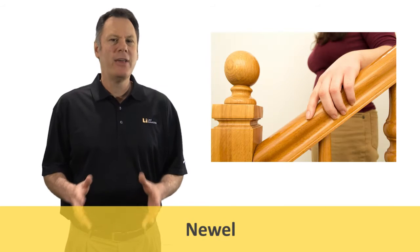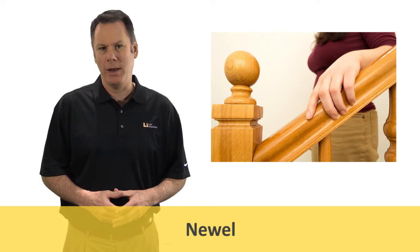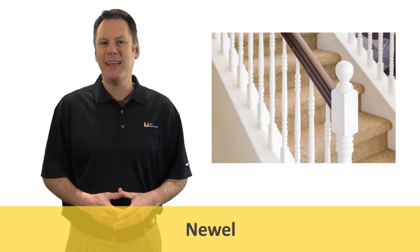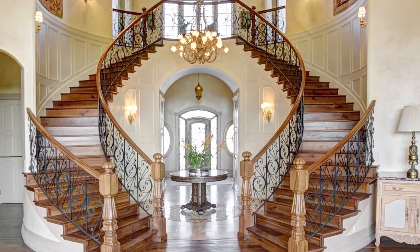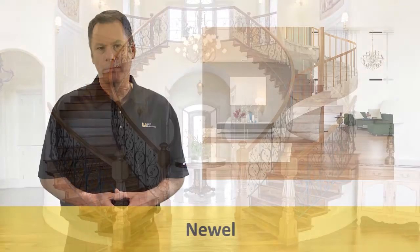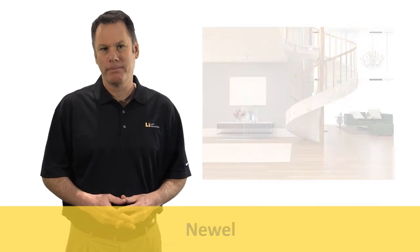Newel, a decorative or structural post member at the start or end of a stair run, often extending above a handrail, usually square or rectangular in cross-section, supporting the end of a stair railing or serving as the common support for two stair railings, often supporting a stair stringer and platform. Also, the center post of a spiral stair.